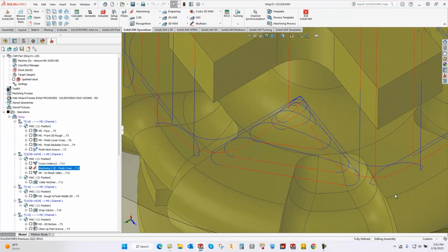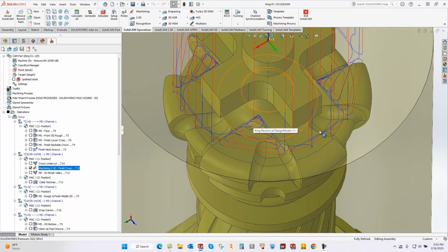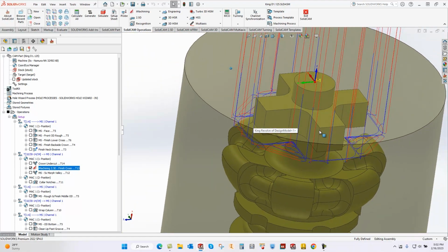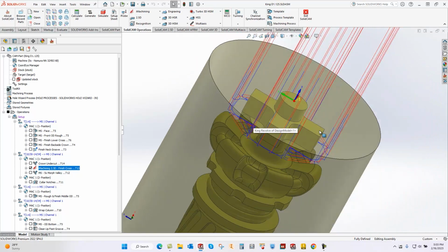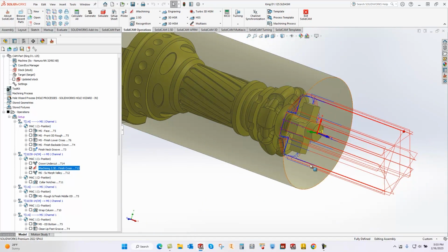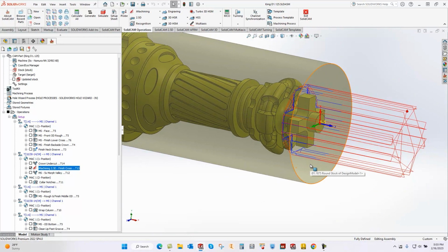So we're doing a series of arcs in there. We're doing things like a high feed rate, an arc off, high feed rate. If you have a bottom face, you can helical up off the floor, high feed rate over, and helical back onto the floor. I'm going all the way through it, so it doesn't really matter in this particular case. But iMachining is really revolutionizing the way you cut. This is a simple preview of what it does, but if you're talking about bulk material removal, exotic materials, or tiny tools, that's where it's really going to shine.